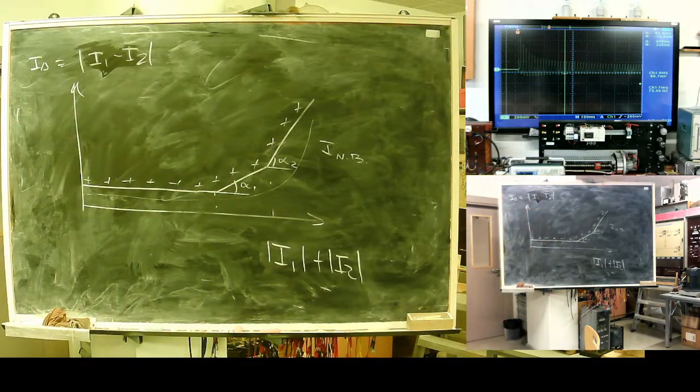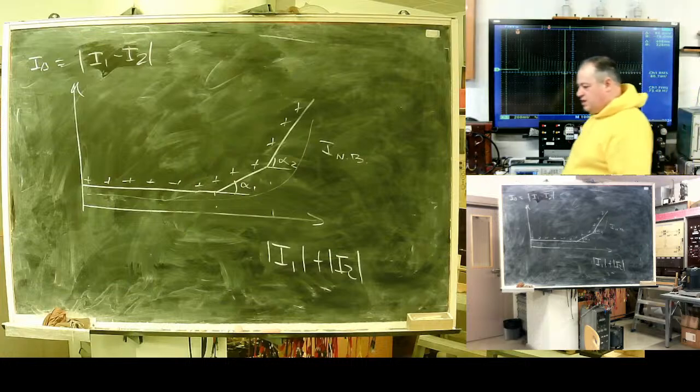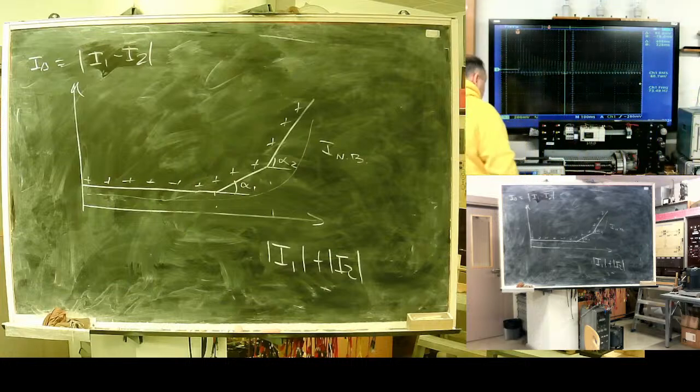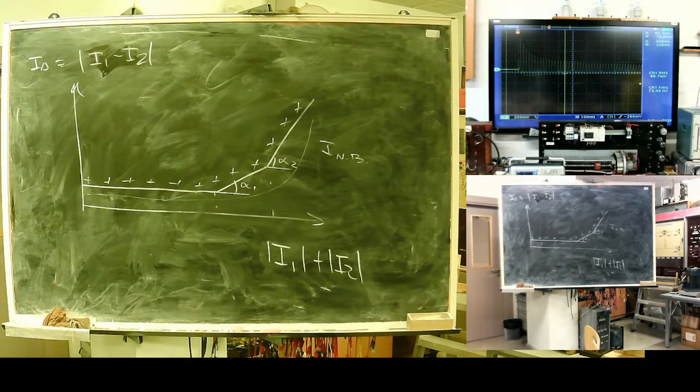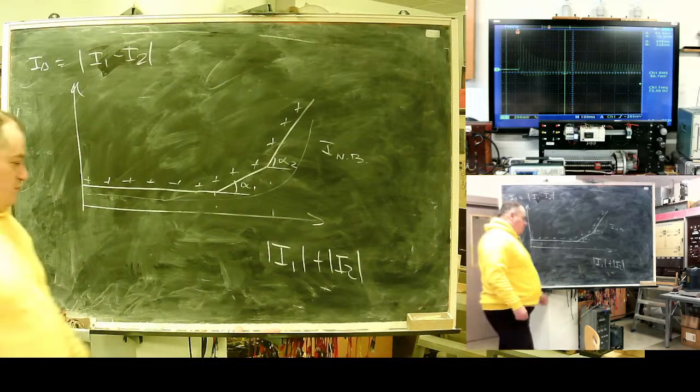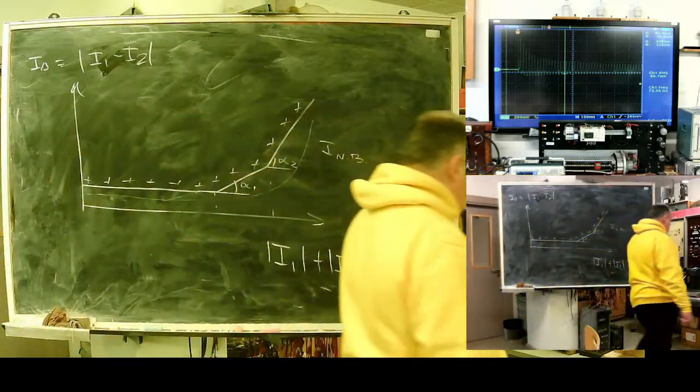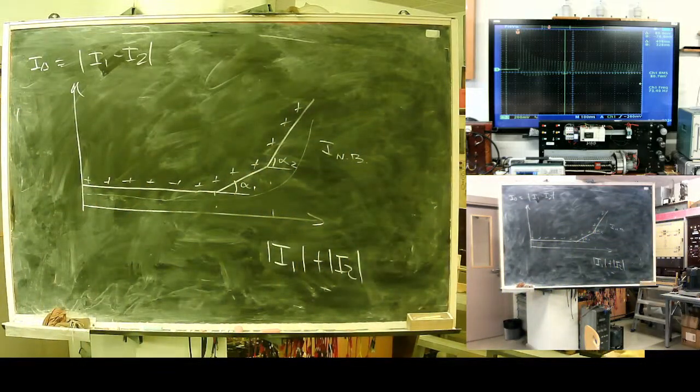Magnetic relays give smooth characteristics. They're extremely reliable, because they survive much longer than other models. But this straight-line characteristic is good, a de facto industry standard for differential protection. But this characteristic itself does not protect from misoperation due to inrush current, magnetizing current.